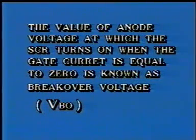The value of anode voltage at which the SCR turns on when the gate current is equal to 0 is known as breakover voltage VBO. Thus, the VI characteristics of the SCR so far have a form like this.